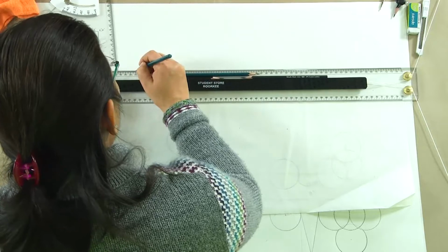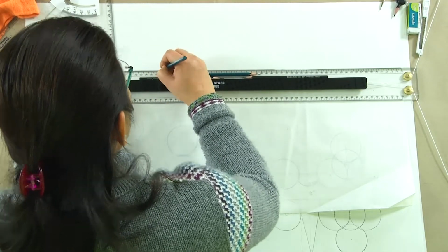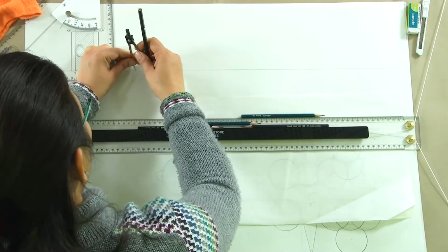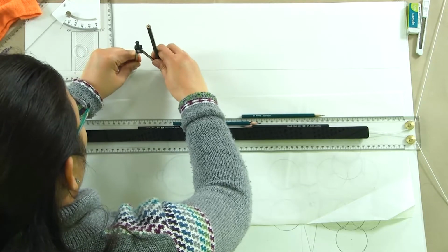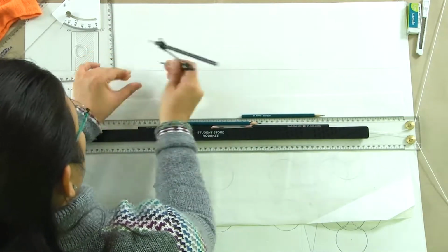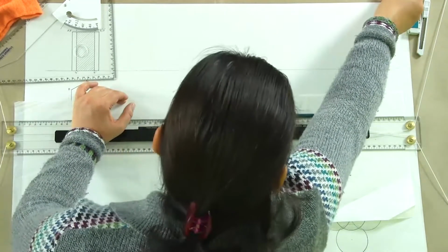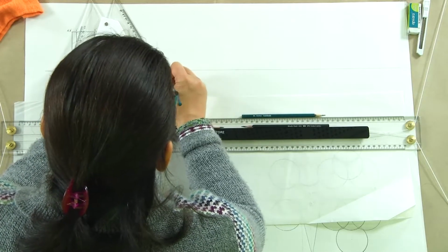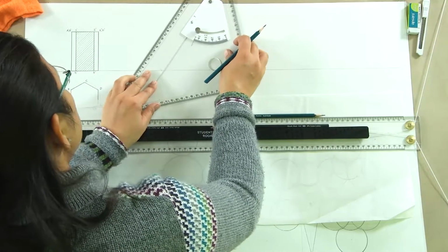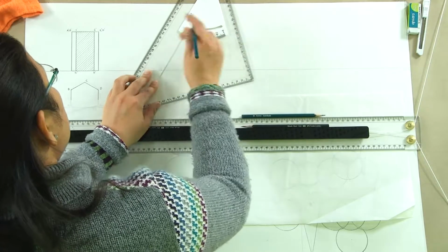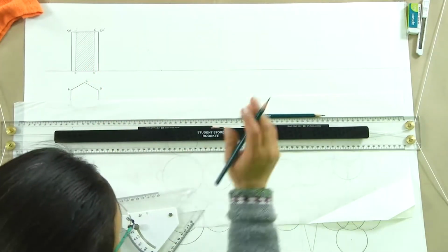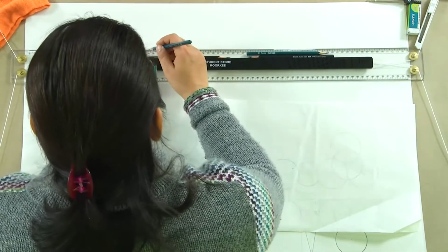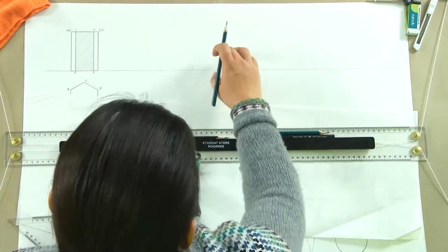Let us quickly take the equilateral triangle. So assuming the triangle to be of 4 centimeter side, I am just drawing it for reference here, or 5 centimeter side. So this is the true shape of the triangle which will be there. However, we will not be seeing it here. So you could also assume it to be the original position which you will be seeing in the side view, or you could directly make it. Now when we see this triangle in the front view, this will be the line which will be the height of the prism.